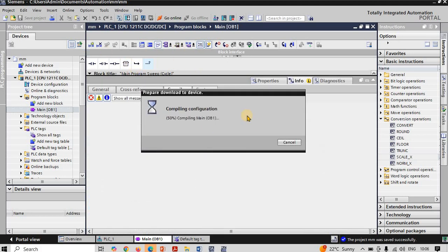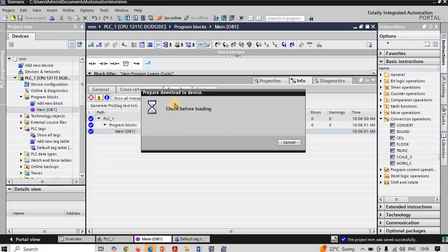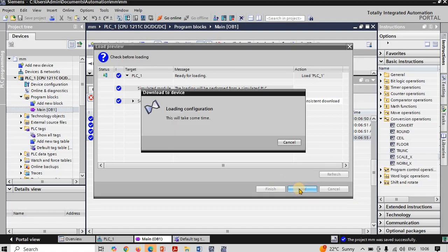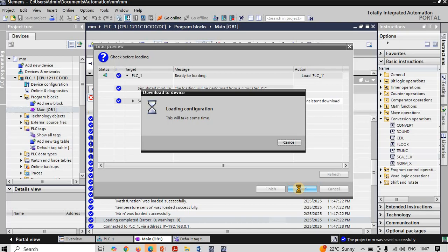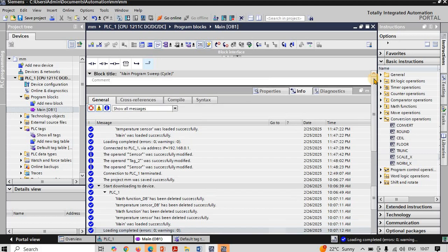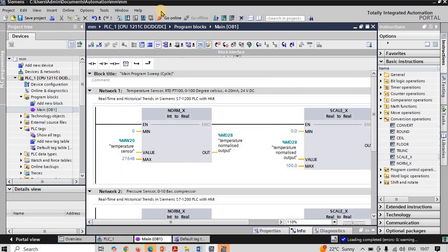And one more thing here, I have designed it for the 2 parameters, right? You can go with multiple parameters, 50, 100, as per the requirement and as per the availability of the analog inputs in your PLC, because if you are just having 10 analog inputs and you are going to design it for 50 analog inputs, that will not work, right? Initially we will have to check the requirement and availability with us, right?